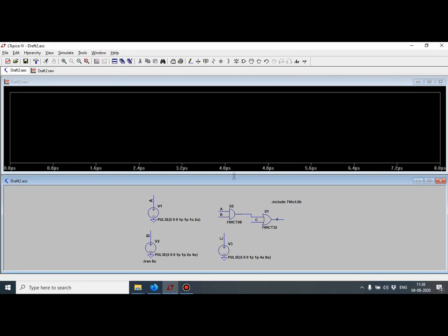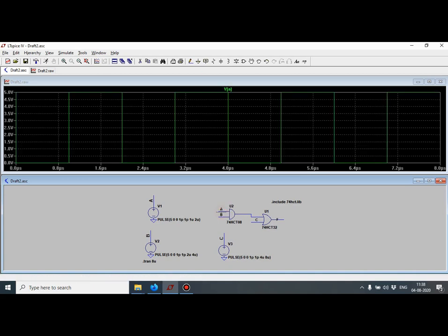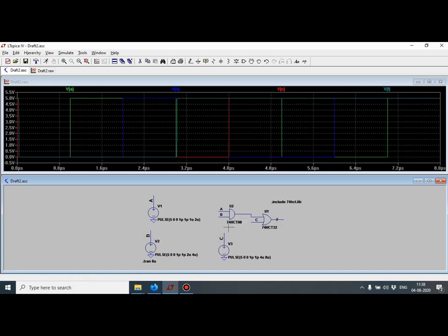So I'll get a waveform window. So this is a blank waveform window. So if you see this, when you move your cursor on the schematic, you'll get this red probe. So I am going to put it on A, and I'm going to put that red one on B, and on C, and on F. The other one also, when you move around, you'll get one more.